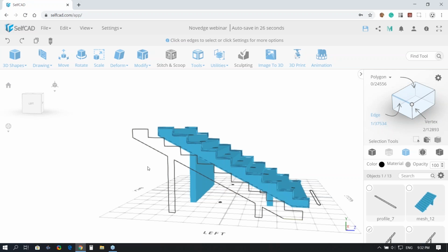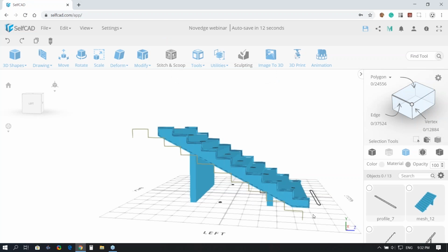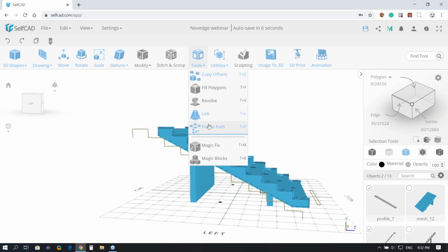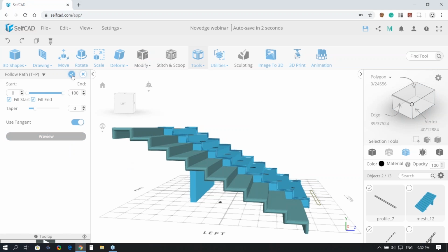So I'll take away this part as an edge, and I'll take away this part, and I'll click delete. Now this entire thing should be found as a solution as a polygon, with the polygon setting, which is minimum cycle. Okay, so now I'm deselecting this, because I need to first select the thing I'm going to rotate around, and I'm going to use Follow Path again, and this basically creates this.